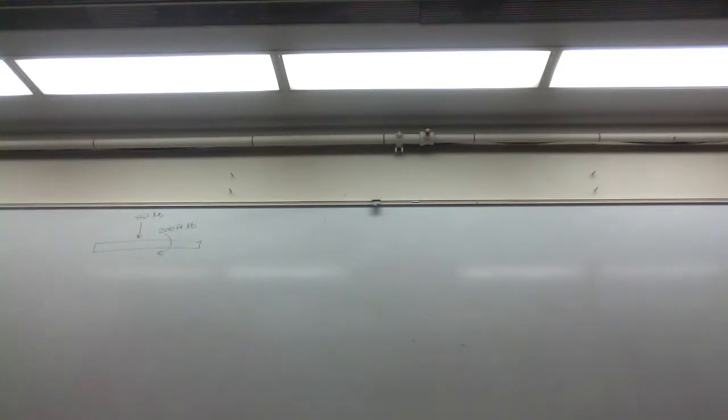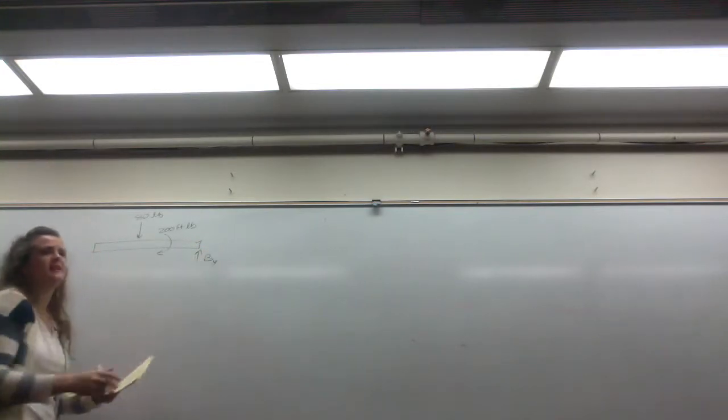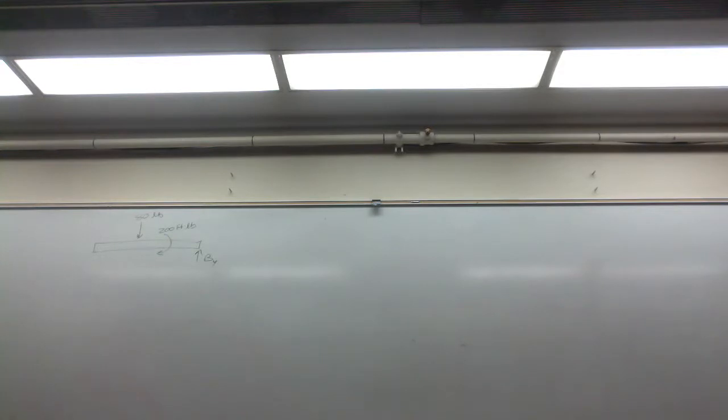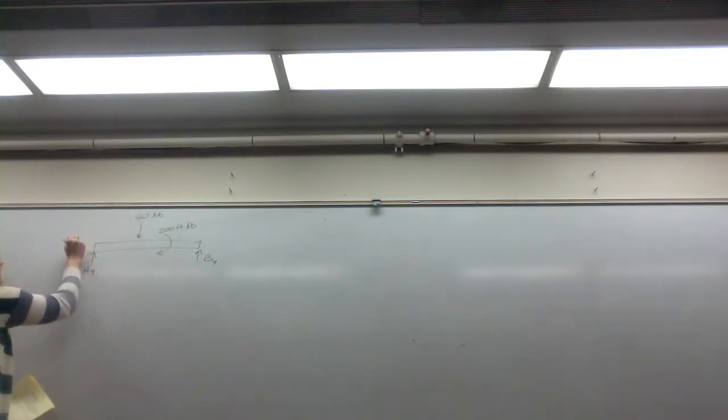okay, what are my constraints? What are the reaction forces? What do you think, Patrick? The reaction forces. An upward force at B. Okay, we're sitting on a roller. It's preventing translation only in the y direction. It's free to move horizontally at B. Good. And the constraint force at A in both the x and y directions.